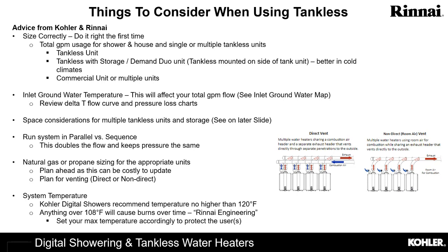For a KOHLER system, it's thinking about things that also tie into how they work well together with the tankless. KOHLER digital showers recommend a temperature no higher than 120, 125 degrees. We always say 120 degrees. It's a great option, and our installation instructions give you that as well. Anything from our Rinnai friends, they say anything over 108, 110 degrees over longevity will start to cause burns over time.